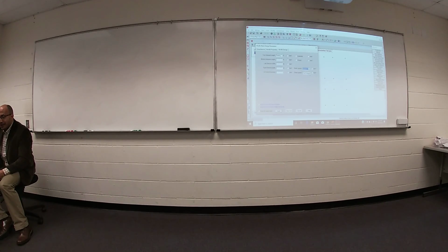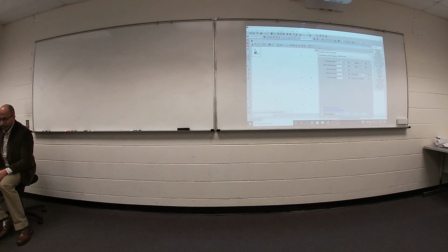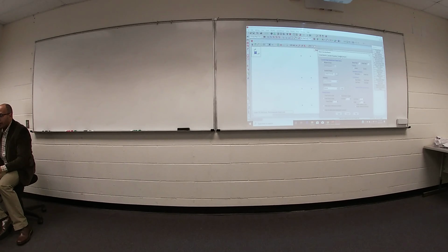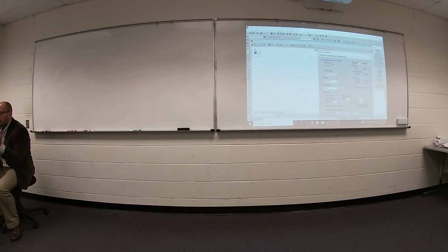So any beam will be drawn today now will have this cross section, which is 16 times 30, and if you modify design, it will have the cross section with reinforcement that you defined before. But I don't like to use this one. I would like to use this software for structure analysis only. Apply. Go ahead and draw your beams.